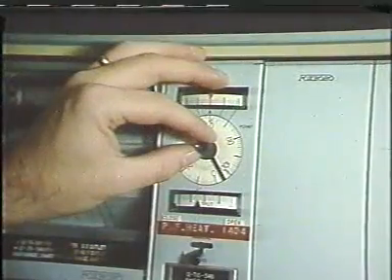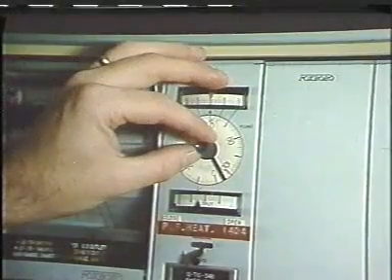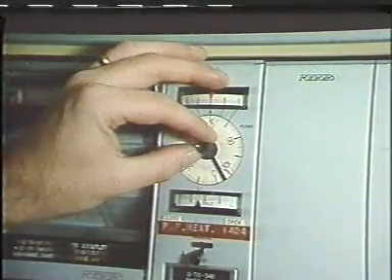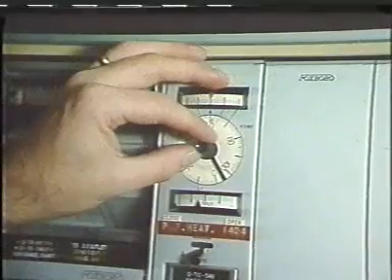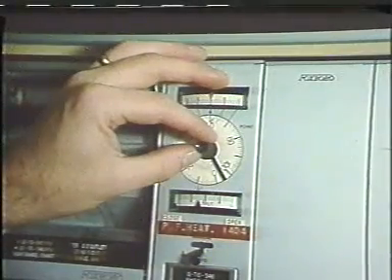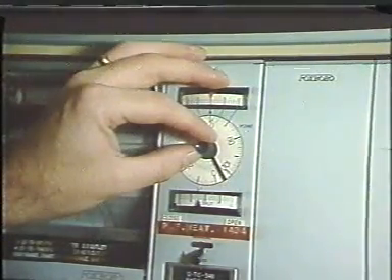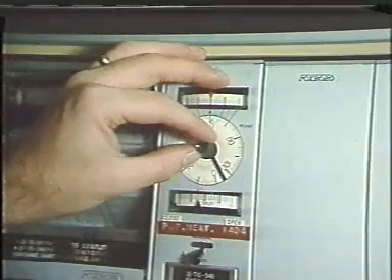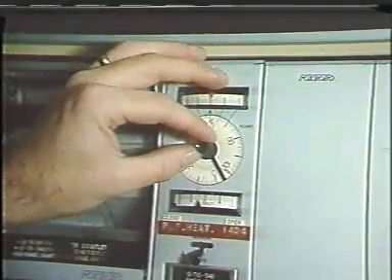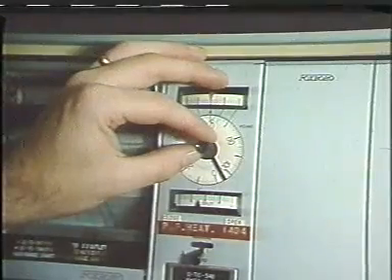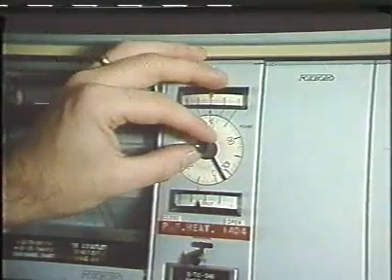As the catalyst deactivates during the course of a run, the octane number of the reformate will often fall below specifications. When this occurs, the reactor temperatures can be increased to bring the octane rating back to the desired value. There is, of course, a temperature limit above which the reactors should never be operated.